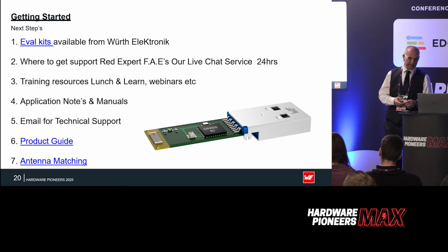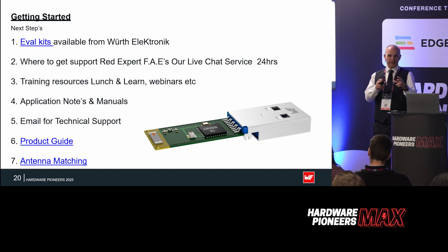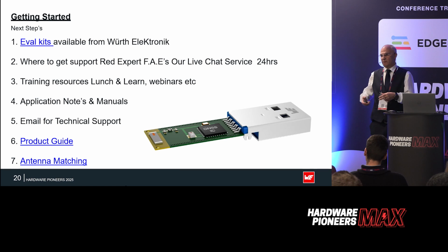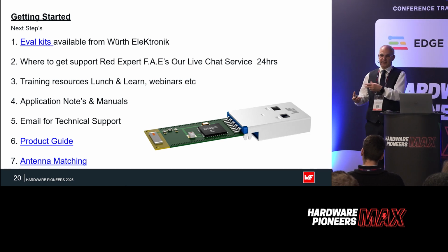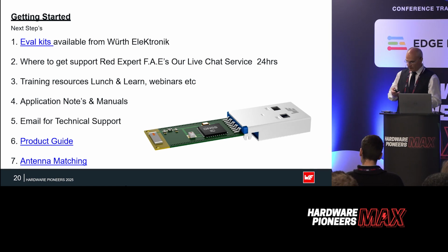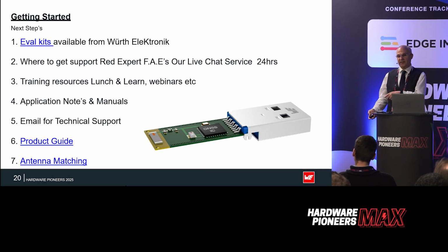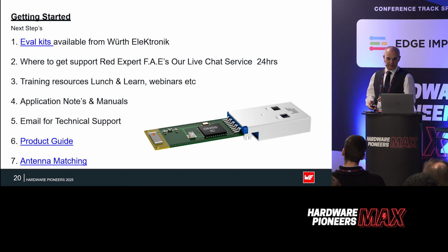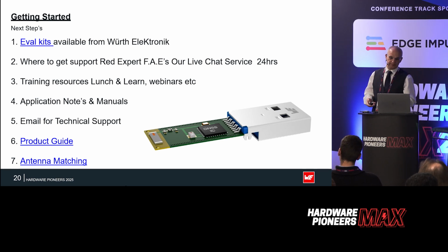And what I would say is the best thing about that is if you can leave your project until you've designed the case, everything else, because being next to your body, being near a case can affect the actual radio performance, and we can optimize it best if it's more closely towards its end stage. But we can make recommendations of what you should do on your PCB, like adding a pi filter on the front end so we can match it easily.